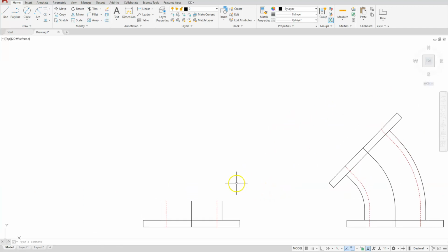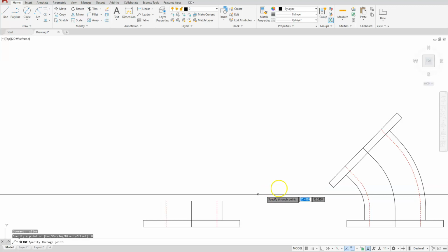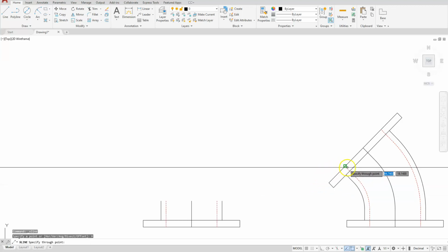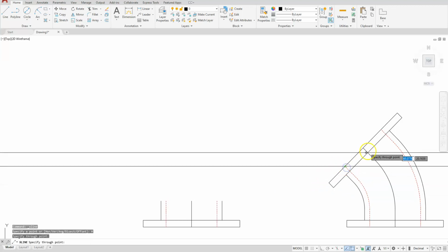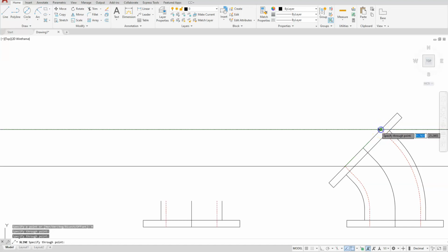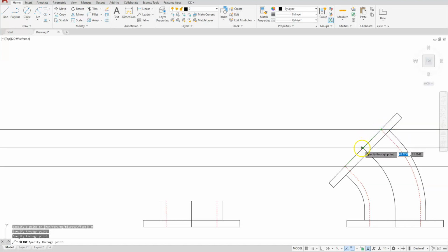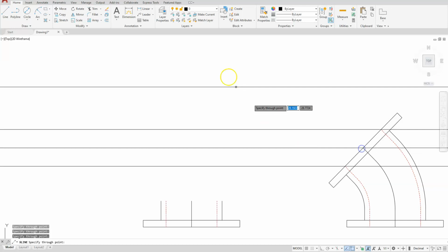So the next thing I want to do is create an ellipse that's going here. I'm going to start off with the one that has a diameter of 10, which is a true 10. I'll select the drop down, choose construction line, horizontal, select this endpoint and this endpoint, as well as this midpoint. Then escape.